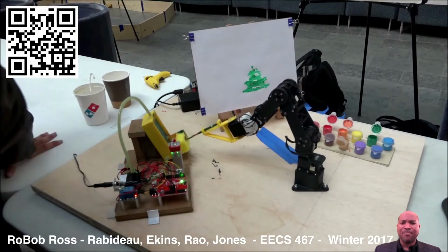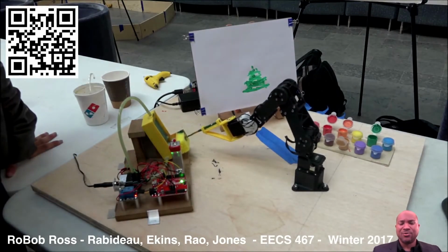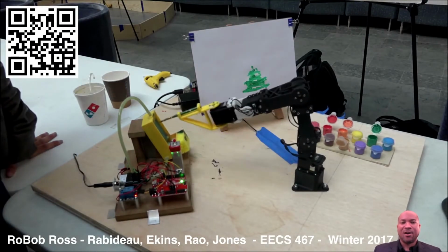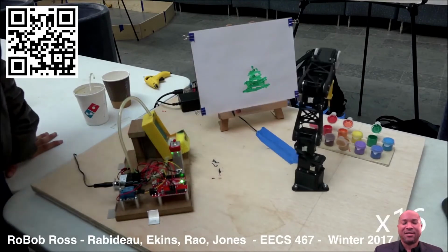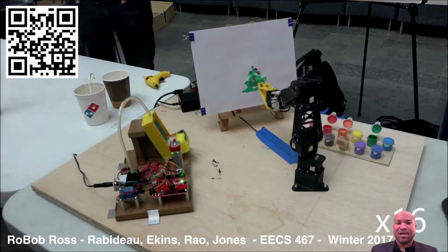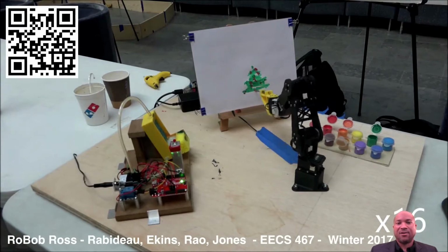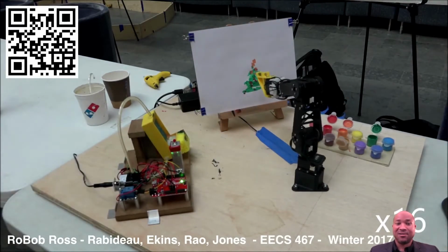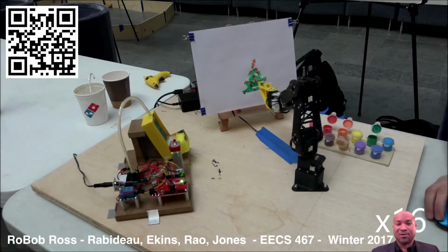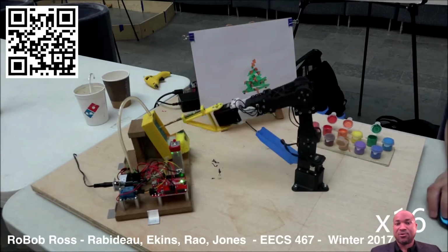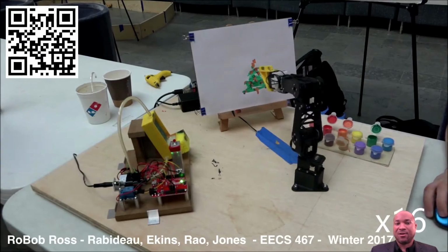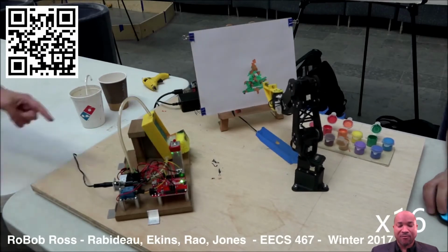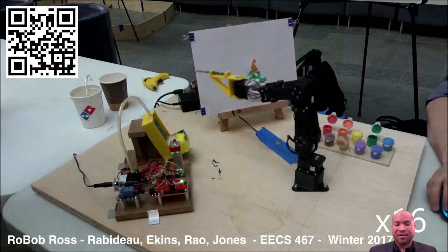In order for this to work, at every joint in this robot arm we have to run a servo, typically a PID control servo, that allows the robot to move its configuration to desired poses, such as hitting a desired target location for the end effector or the tool, so the robot can perform in a functional way.